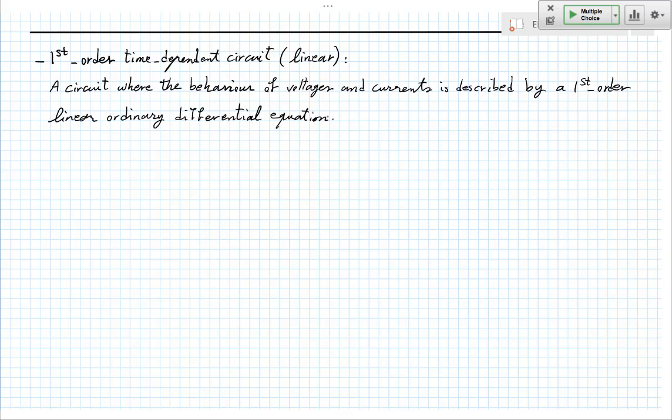Maybe in parentheses here, I should say that if you go to circuits where you're dealing with frequencies in signals, such that the wavelength of the signals involved is actually comparable to the circuit dimensions or larger, then you really are dealing with electromagnetic waves traveling all over the circuit.